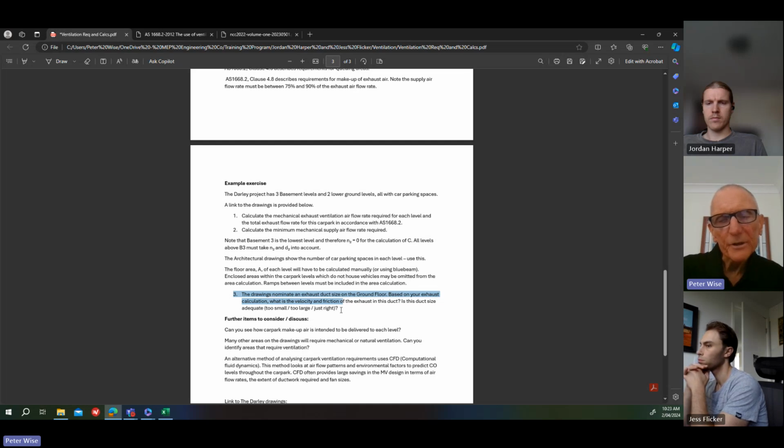Do you think that's right? I mean, we can talk about that when you've worked that out. And based on information that I gave you previously, you might be able to say, let's say 8 meters a second is okay, or maybe 10 meters a second is okay, because it's quite a large duct. It'll be a large airflow, but you find that as ducts get bigger, the friction rate is coming down, but the velocity is going up. So it's really what's the best solution there. And really what we're trying to achieve is the best solution for the lowest cost.